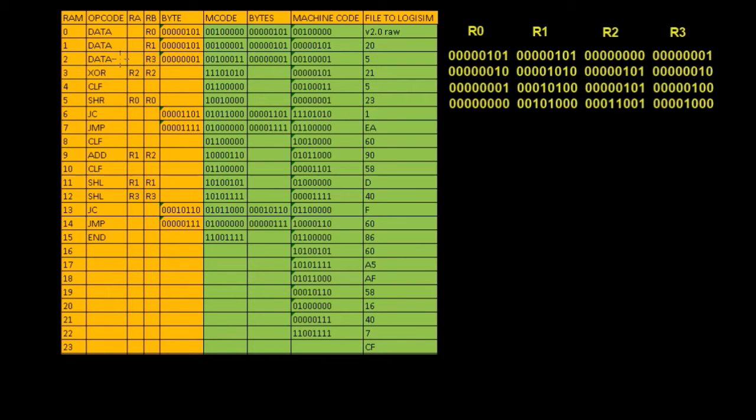Now we're going to use register R3 as a little counter, because it's going to be working through a loop, and it'll work through 8 times. Originally R3 starts off with a value of 1, and then it works its way up the significant bits until it gets to the very end, and when it's at the very end we know we've gone through the code 8 times, and then it will jump out of the loop. So that's just for counting purposes.